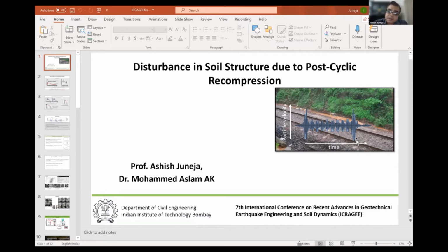And lo, all the embankments they perform successfully. So in a way, there has to be a certain background to it: the soils have been subjected to cyclic loads from the railways. As an example, you see the high frequency loads which come from the railway track, the wagons and the engine, especially the engine. Because of this subjection to these loads, the soils below have, over the period, undergone deformation. As a result, their bearing capacity or strength has improved. So we are looking at what soils, the improvement, and at least to quantify those numbers.